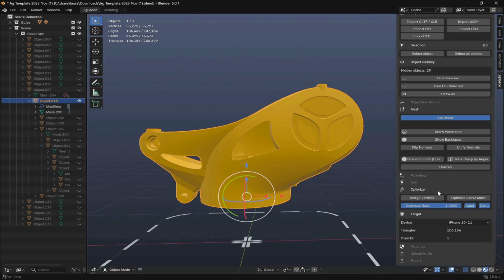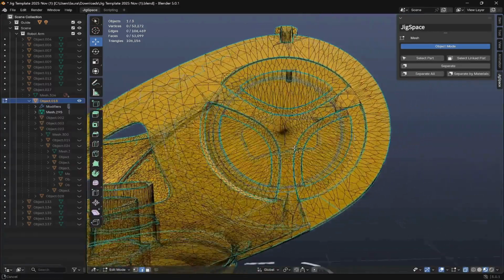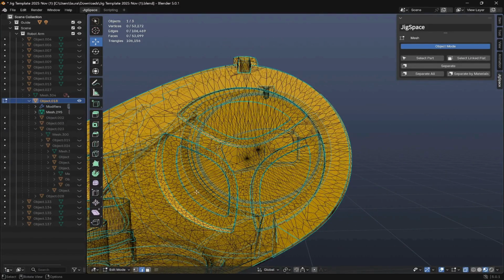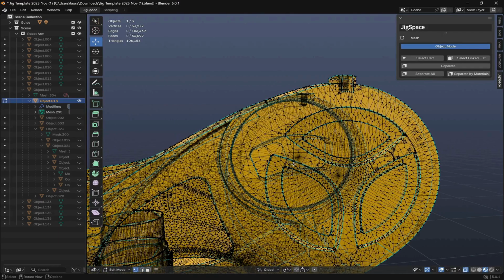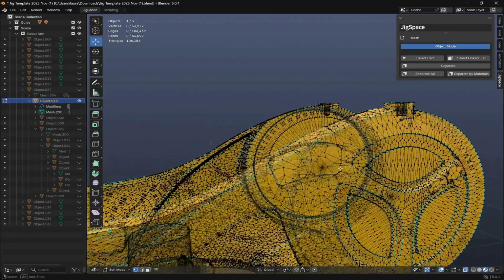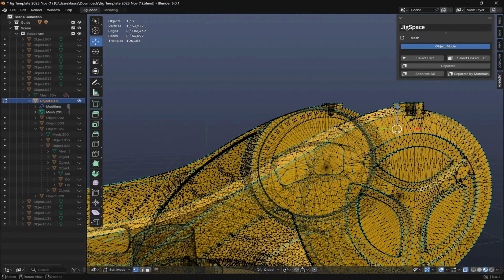Now, with some 3D programs, you may find that certain STEP files or other BREP 3D models don't always have their vertices fully merged. And to give you an idea of vertices, if I select my model and go into edit mode, you can see currently this model is made up of that mesh of triangles, but if I press 1 on my keyboard, that's going to bring up my vertex menu. And each of these dots represents a joining point where those triangles meet.